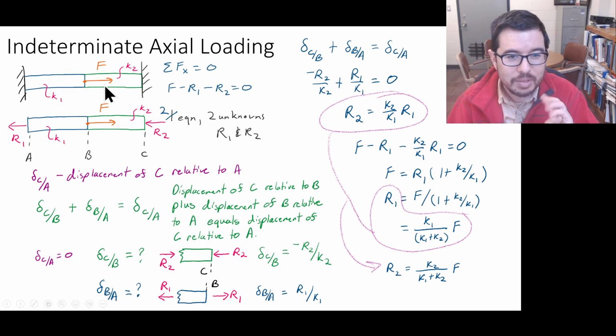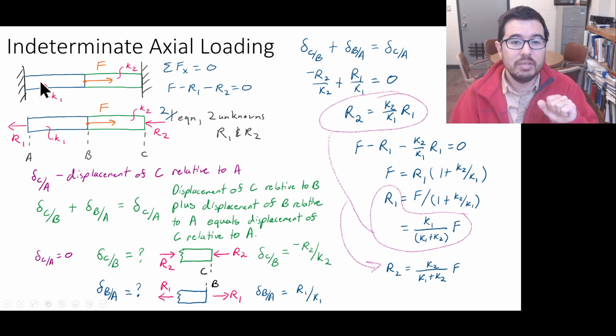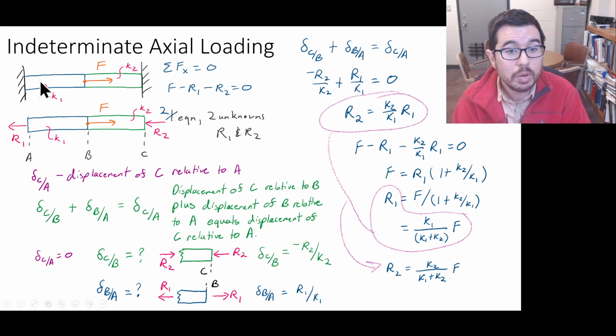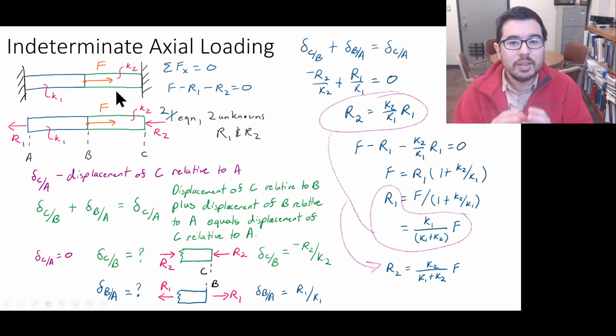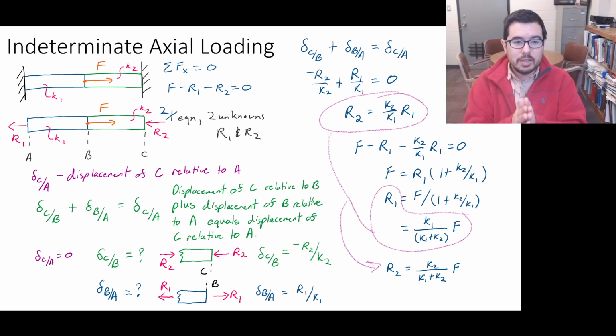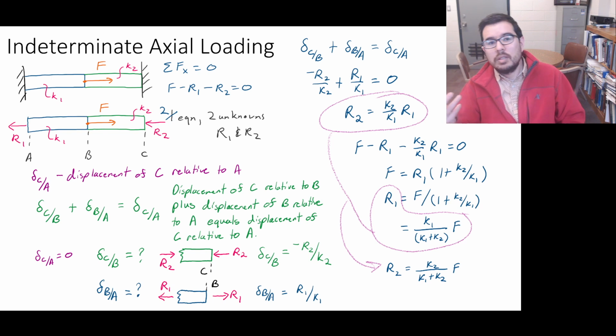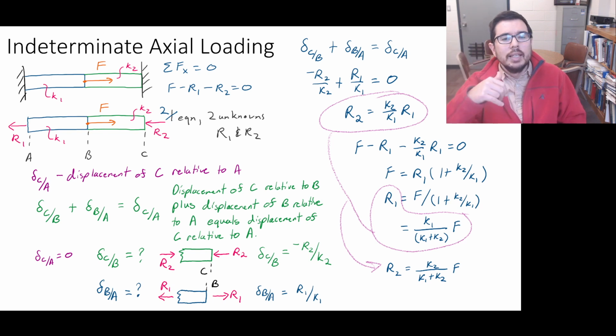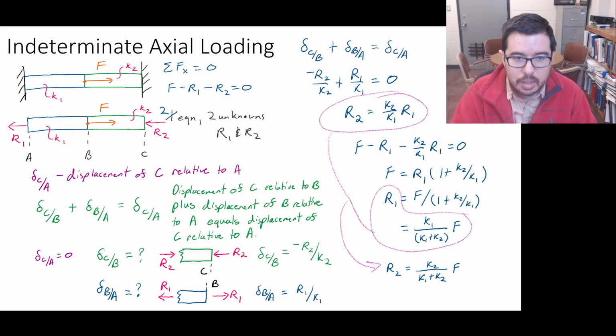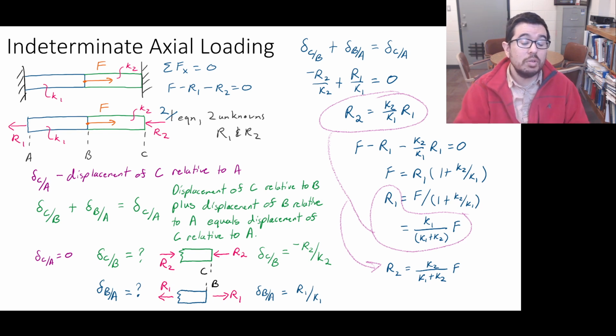stiff, less stiff, means that this side is going to have a higher force embedded inside of it than the right side will be. This is a very interesting and powerful concept, thinking in terms of stiffnesses. Often we think, stiff is stronger, right? And yeah, something that's stiffer has generally more cross-sectional area for a given material. And so, yes, that could be true, but it could also be supporting a higher force.